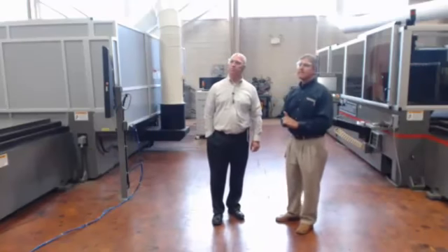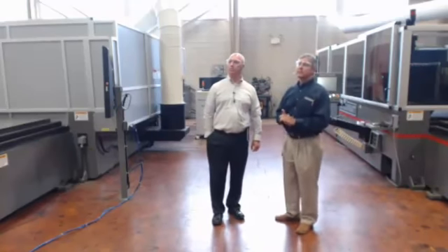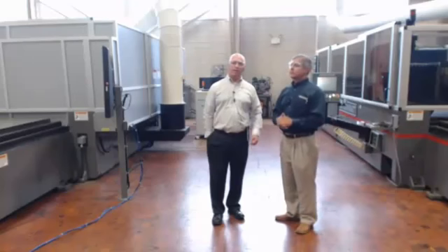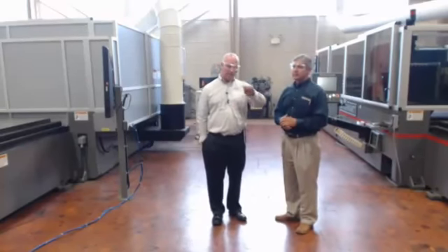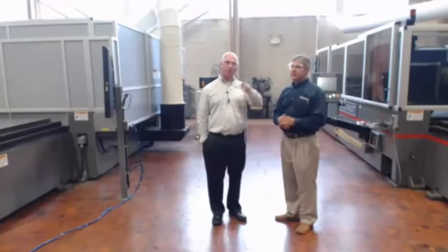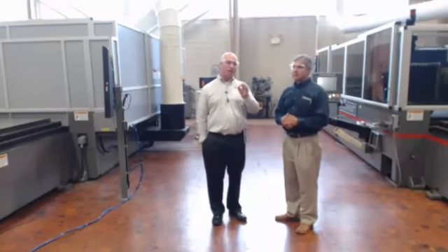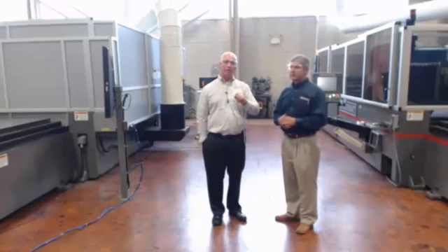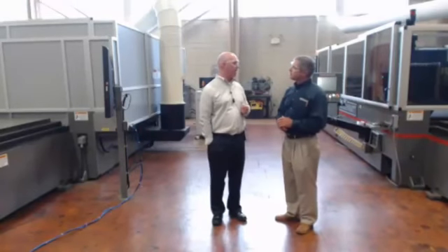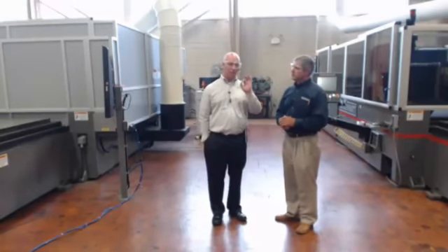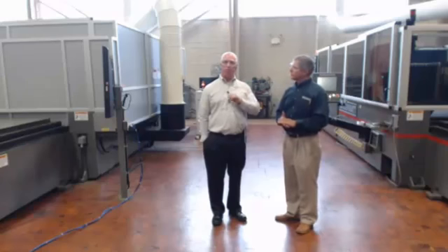Had another question on fly cutting, asking what the advantages of fly cutting were again. It's eliminating pierces on each internal contour. We're also not stopping and cutting around each internal contour; the motion of the machine stays consistent as it goes up, and we don't have that pause right at the beginning. When we get to the contour, the beam turns on. We are cutting thin gauge metal, and that's really about the only time you're going to be able to use a fly cut, when it's thin and the pierce time is almost negligible.